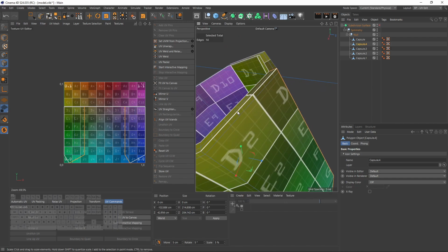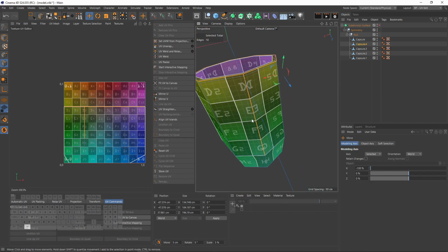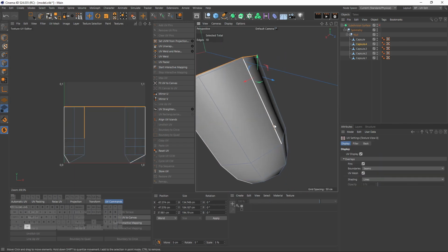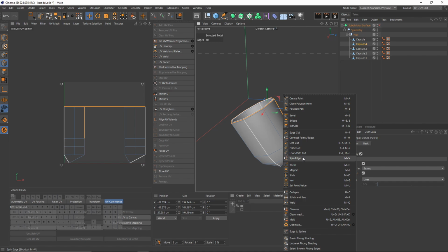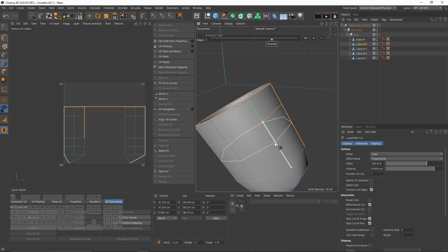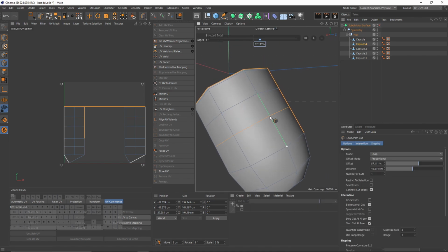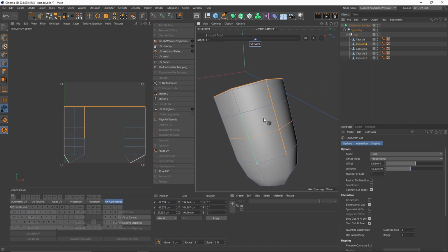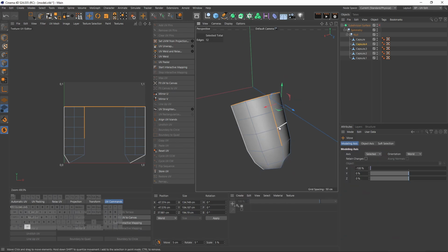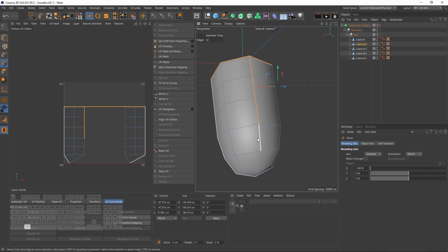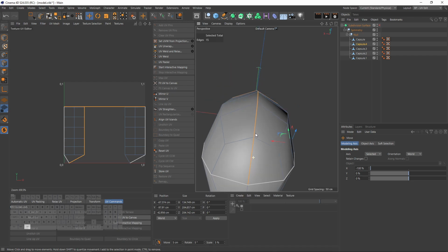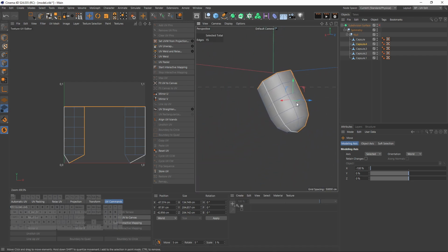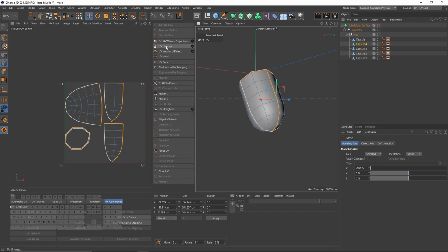First thing, let's select sharp edges. Then I will select my seam. But I forgot to add some loop cuts like these ones. These are very important. These are gonna prevent my texture from stretching. So let's not forget these. I will select these ones. Then say UV unwrap.